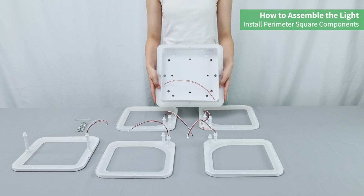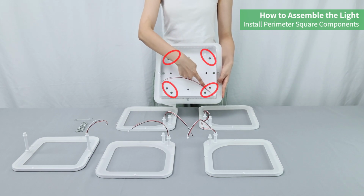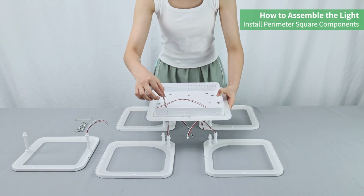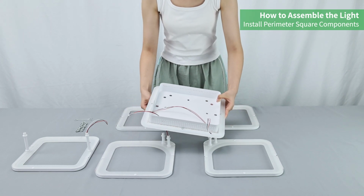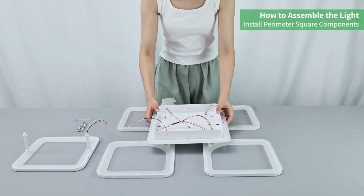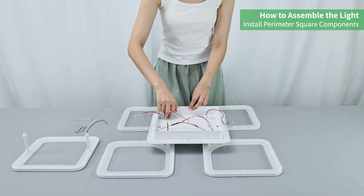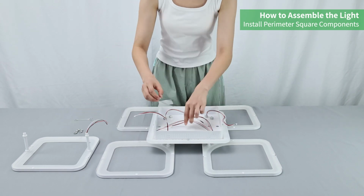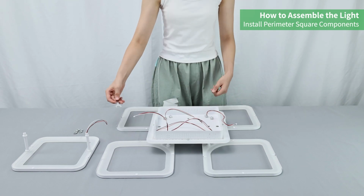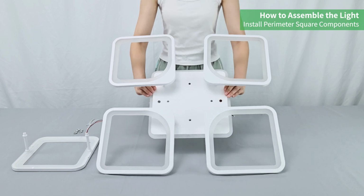Install perimeter square components. Align the square components with the short tubes installed with the 4 pairs of holes on the perimeter of the chassis. Make sure to thread the wire through the hole first, then adjust the position of the fixing tube on the center square component. Use nuts to secure the components to the chassis. Finally, use a small wrench to tighten the nuts. This is what the perimeter square components look like when installed.